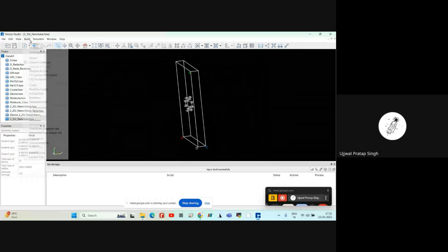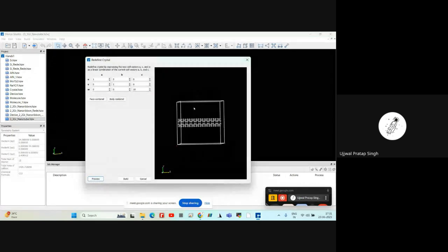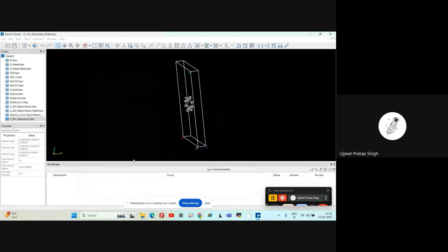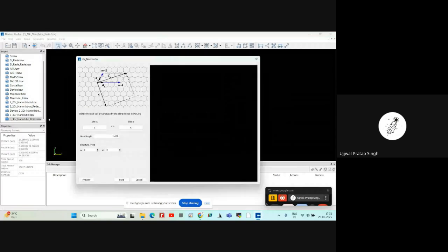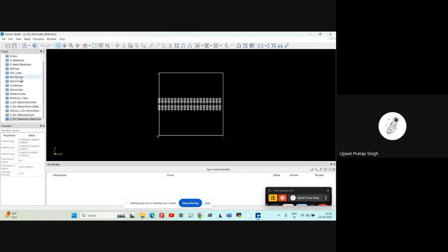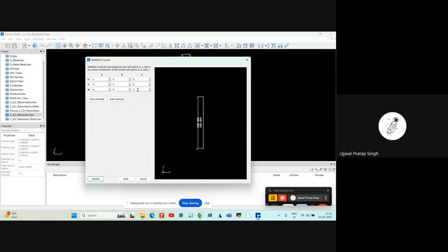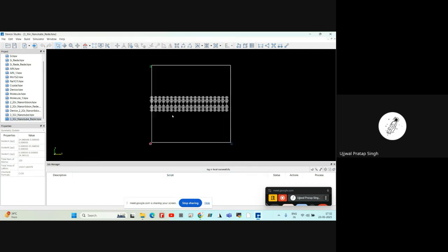And in the same way, build option, redefine, and in the C direction if you want, you can redefine your carbon nanotube. And click on build. Again, I repeat, first go to the build, then graphene nanotube, then go for the 3x3, then preview, and after that, to show the structure like this, go to the build, then redefine, and in the C direction, go for 10, and then 50. It's basically a 3x3 graphene nanotube structure.